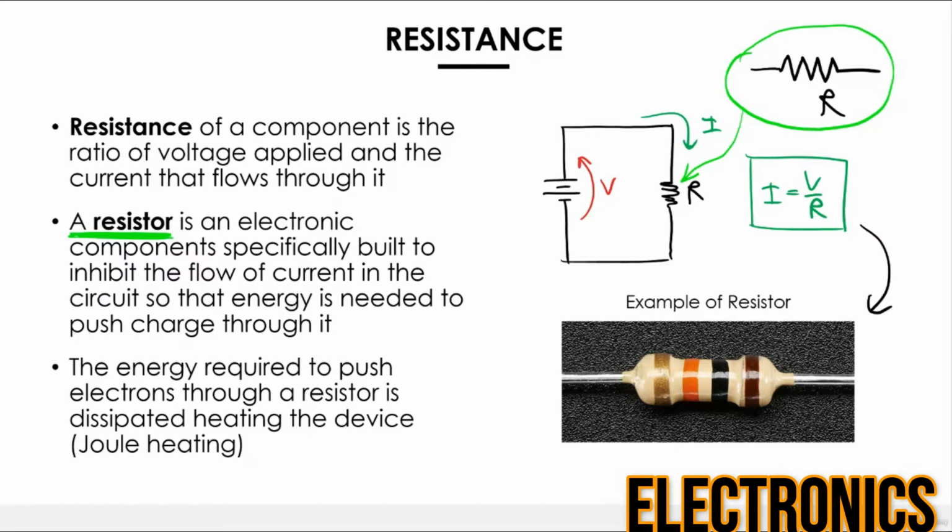As we said before, you put it in a circuit. If you know the voltage across the device, you can calculate the current very easily by dividing the voltage by the resistance. And vice versa, obviously. If I tell you the amount of current going through the resistor, you can immediately calculate the voltage across the device by multiplying the current by the resistance.